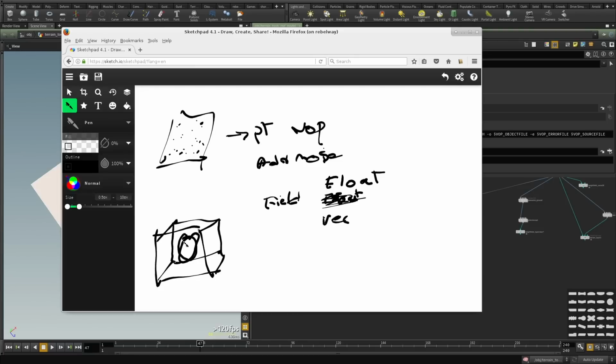So the way we see data in Houdini, the volume, we generally look at the density field, and then if we have other information, we can take that density field and colorize it with other attributes to visualize them. And the density, let's say we have a sphere. What happens in this domain is that all the voxels that are in this space will get a value of 1 for the density. Everything else will get a value of 0. Now the data is present only here. Only specific voxels have a value of 1.